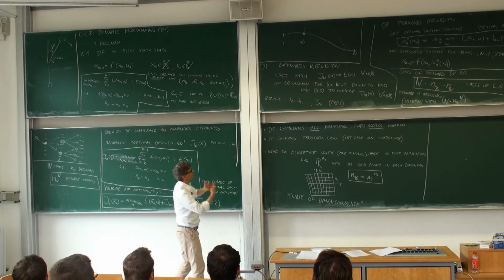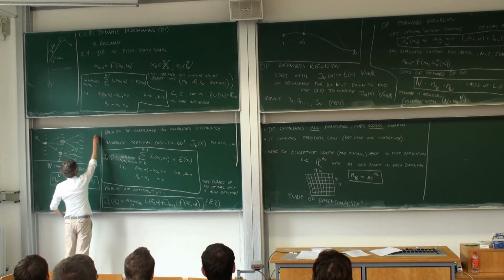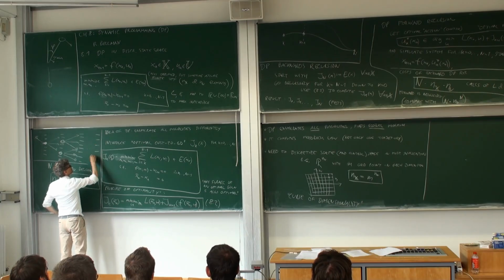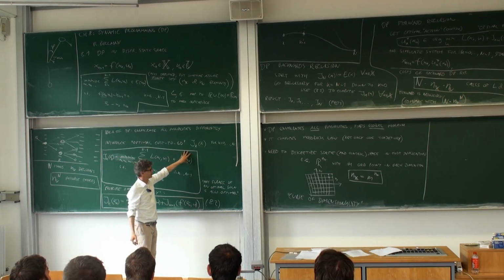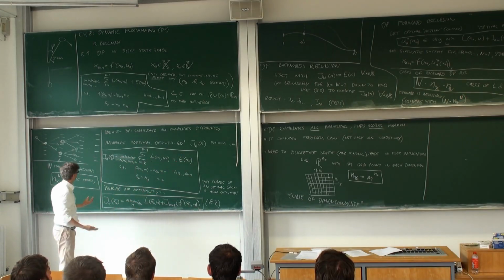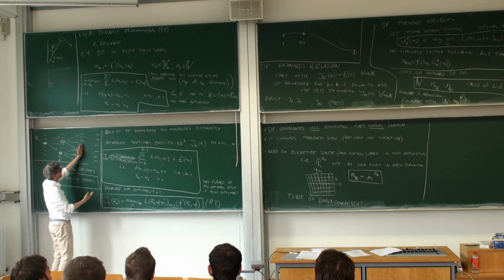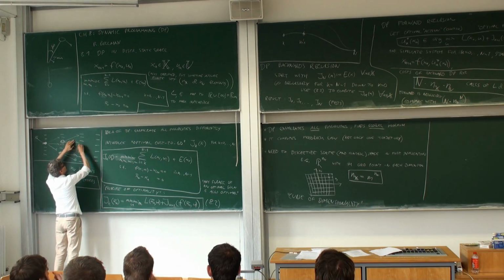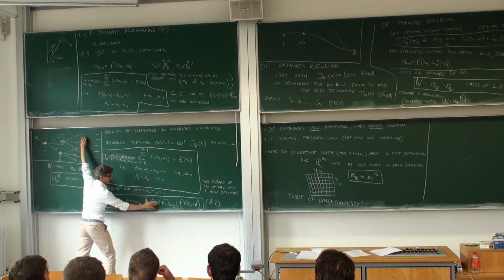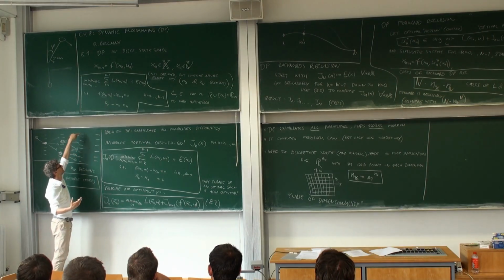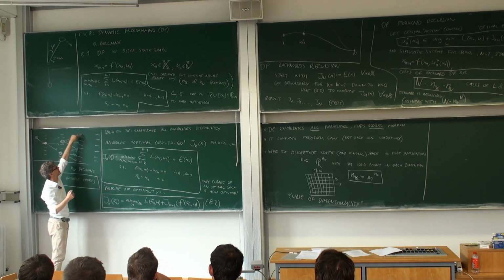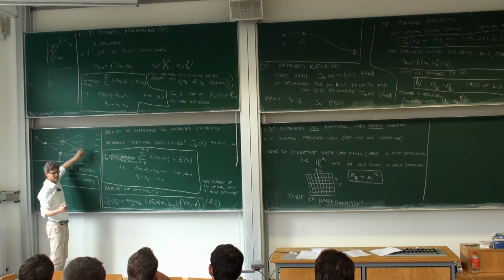So you start with the cost to go at the very end of your horizon. At the very end, you know what your cost to go is, because you will just have the terminal cost. Yeah? There is nothing to do. But then, for going one time step back, for each of these states, you compute the cost of the step plus the terminal cost, and when it is minimized, the minimal value I put as a number in this location of the vector here. So I will actually just have nx numbers as the result of each of these DP backward steps.